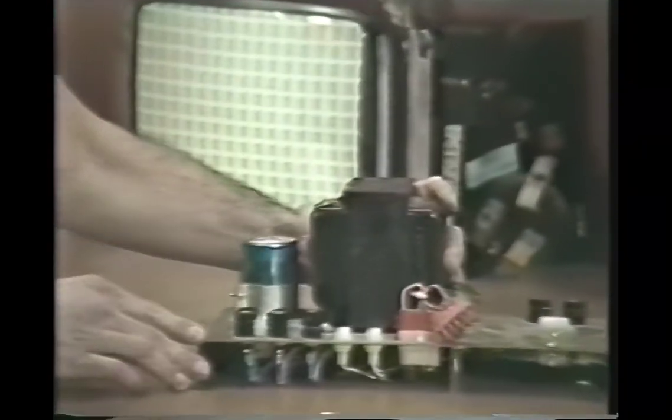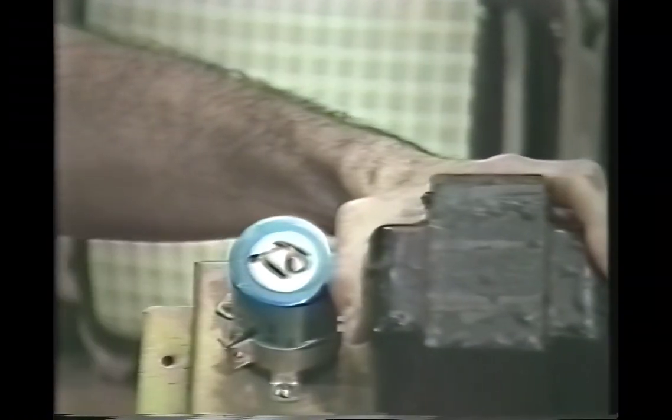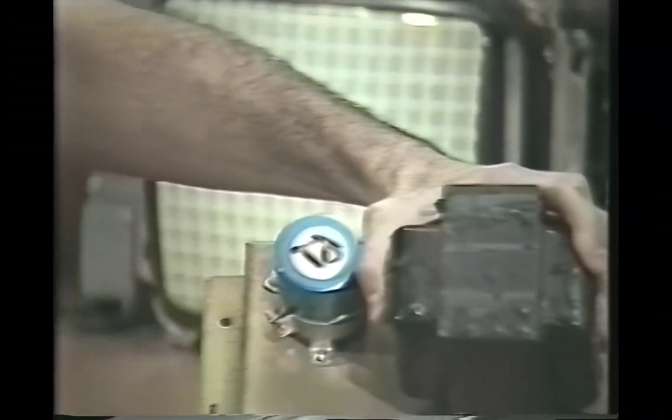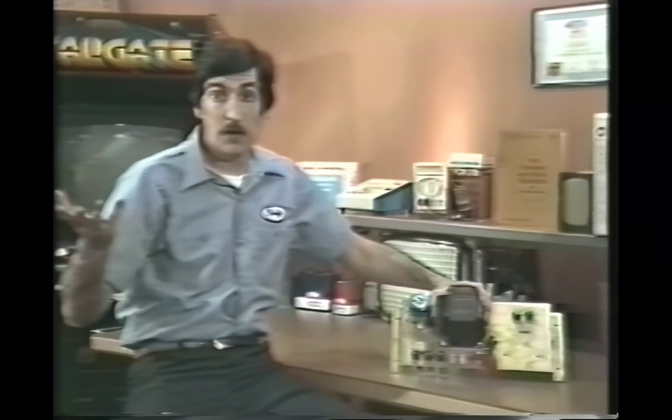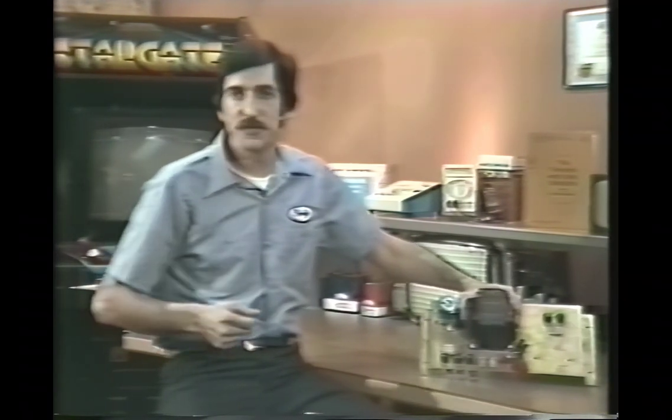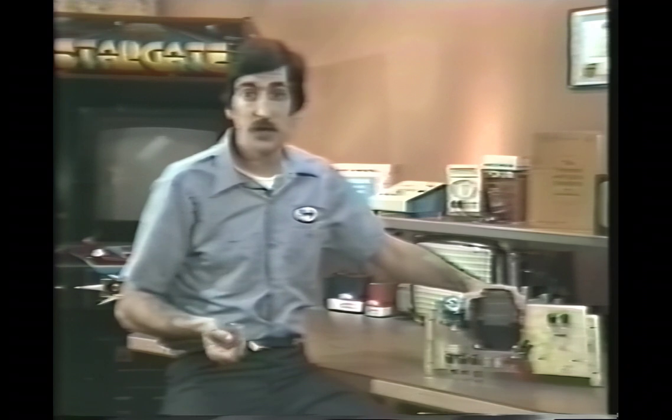The capacitor is this blue device right here. The capacitor is like a short-term battery that accepts a charge when there's power available to it, but when the power output from the diodes drops down to 0, the capacitor takes over and keeps that voltage constant across the rest of the devices in the game, such as the computer or the sound system.